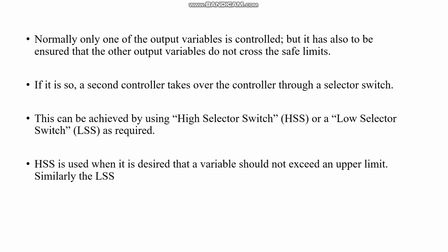If they do, then the second controller takes over through a selector switch, by using a high selector switch or low selector switch. The second controller takes over there.